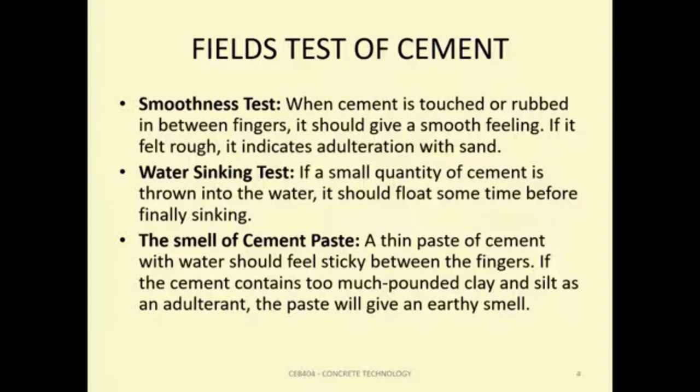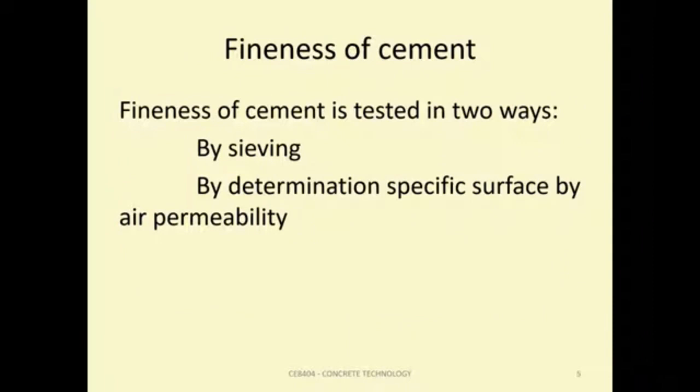The next one is the smell of the cement paste. A thin paste of cement with water should always be sticky between our fingers. If the cement contains too much clay or silt, it is an adulteration, and the paste will smell like an earthy smell.